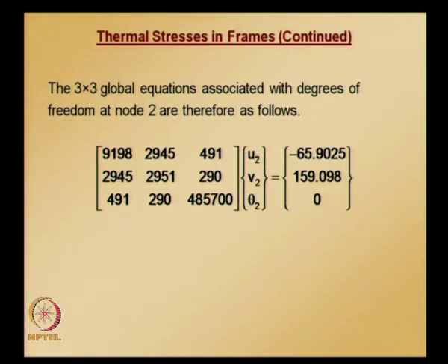In the global load vector that we got, the values at locations 4, 5, 6 are taken as the load vector for the reduced equations. The stiffness part is obtained by adding the lower quadrant of the element 1 stiffness matrix and the upper quadrant of the element 2 stiffness matrix, because that is the contribution that goes into the locations 4, 5, 6 rows and columns in the global equation system.